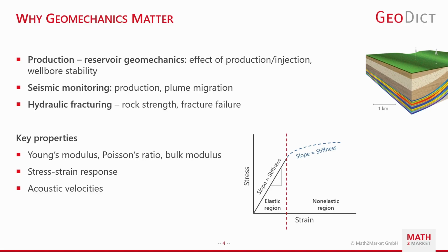So some key properties for this are Young's modulus, Poisson ratio, and bulk modulus. I'm sure most of you are aware of. And there is the complete stress-strain response, including both the rock's failure in the non-elastic regime and, for example, sometimes also plastic or viscoplastic deformation. Also, there are the P and S waves, or the acoustic velocities, that, as mentioned, are related to seismics and interpretation of fluid saturations in the rock.